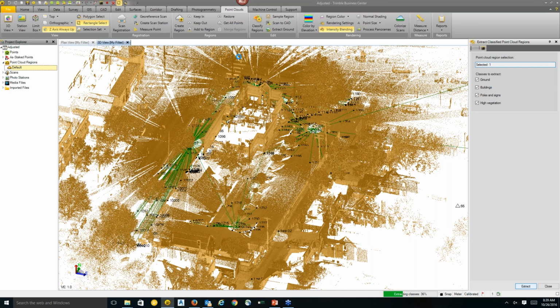If any of the regions are classified incorrectly, which is likely to happen in a lot of cases if you don't have dense point clouds, as the more points you have and the higher the density, the better classification results you're going to get. So you can't expect to take a really sparse point cloud from, let's say, an S7 and perform this command on it and get high quality results.